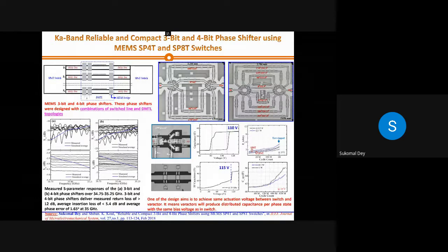And the challenge is what? The challenge is that you have to design the switch. Now, how many control elements do you have? The 2 SP8T switches are giving you 16 control elements. The varactor you don't count as a control element because it is not giving you complete actuation. You just need to tune it with some voltage. The beam will never come down and touch the signal line, otherwise your entire signal will be grounded. So check that these varactors are connected to the ground. You just need to give some actuation voltage by which you can get your required phase shift.